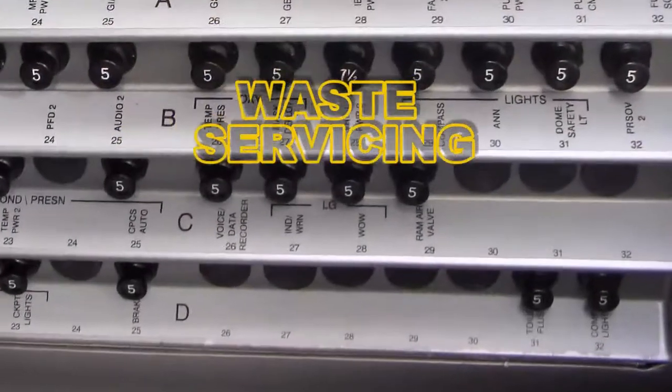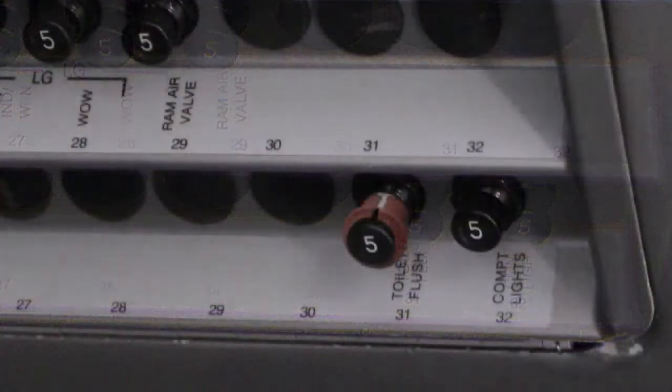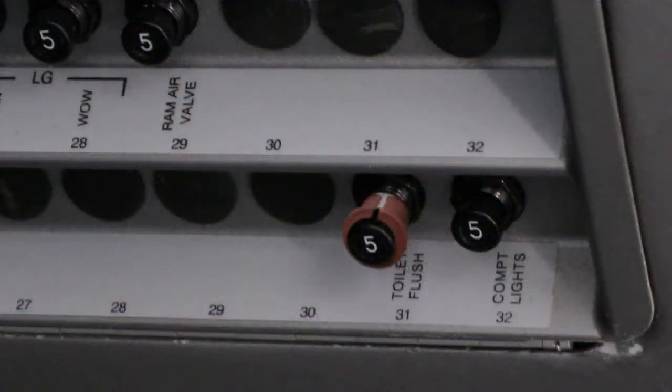Waste servicing. Open the toilet flush right-hand circuit breaker panel and put a tag on it. Pull the toilet front cover to open it. The cover is attached to the toilet shroud box by a lanyard. Push the manual closure valve to close it.